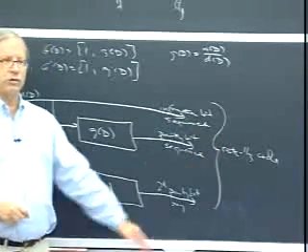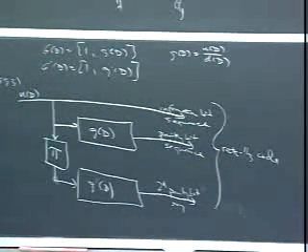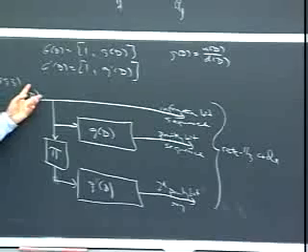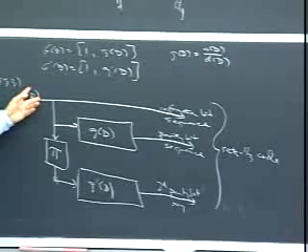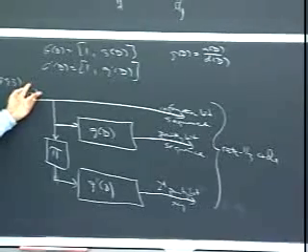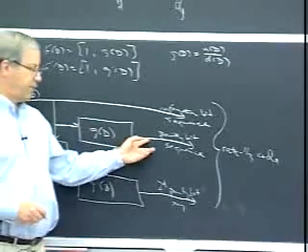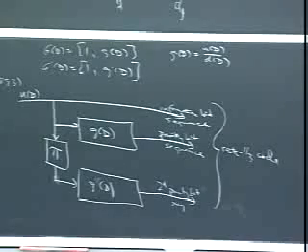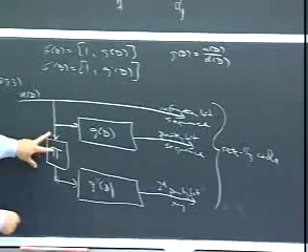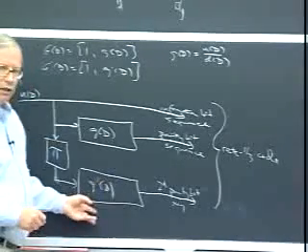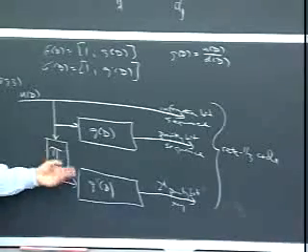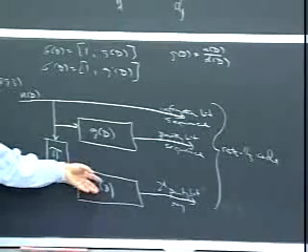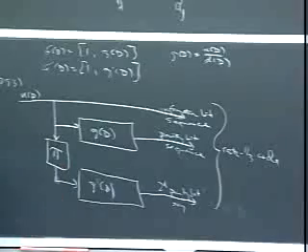The impulse response to a single information bit is infinite. It takes at least 2, and you can prove to yourself there's always some sequence of length 2, in order to get a finite number of non-zero parity bits out of here. And then when those 2 bits are permuted, they're going to come up in totally different places, so they're going to look like 2 individual information bits down here, and therefore they're going to ring for a very long time.